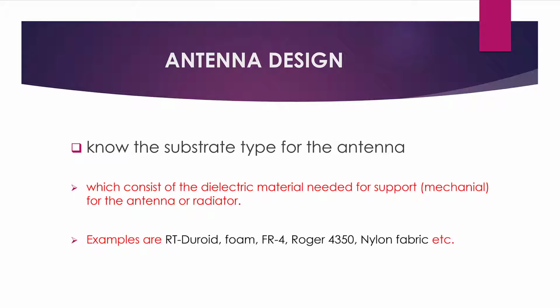Right, so the FR4 substrate is the optimal solution for minimum size and price, since it is very cost effective and has a much smaller size, but it is sometimes requirement dependent. All right, so you should know what you want so that you can choose the right substrate for your design. So this is very key when it comes to antenna design.